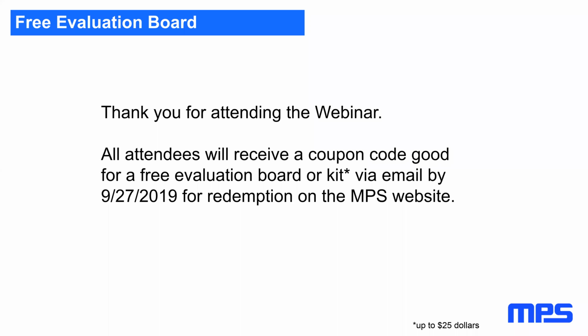Actually, on this plane, because it's only a 1 amp design, I used only one via. However, you can also use a via block with more vias close by, or a direct connection on the second layer, where you go from the noisy ground to the close ground. But this connection should be at a place where you define where you want your quiet spot. That typically should not be in the middle under the hot loop, but a little bit aside from that, as is the case here.